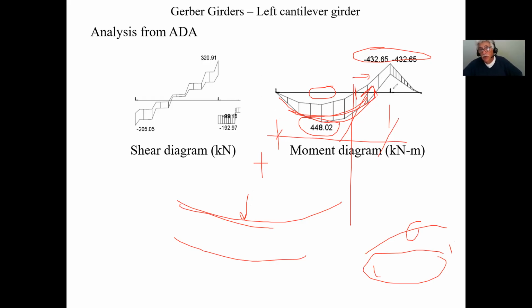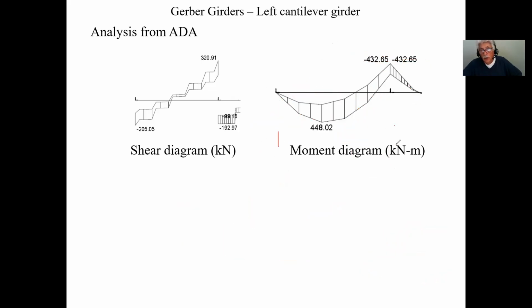So when you have this situation, because this is in compression, in other words, here, the top flange is in tension and the bottom one's in compression. Here, the top flange is in compression and therefore here, the joists are supporting the top flange, but here, the one that's in compression is no longer supported. And therefore our LU becomes the whole span because of the negative moment here, okay? And that all of a sudden gives you an unbraced length of the whole span, which would be 10,000 millimeters. So that's number one. That's the first thing you should realize when you see these diagrams, okay?